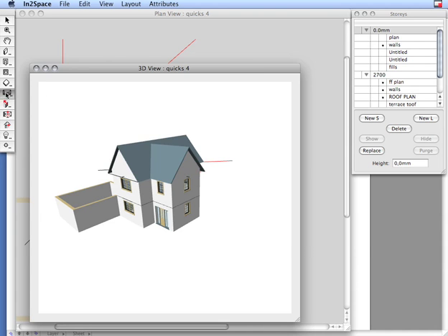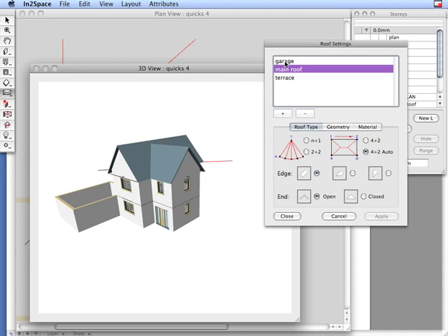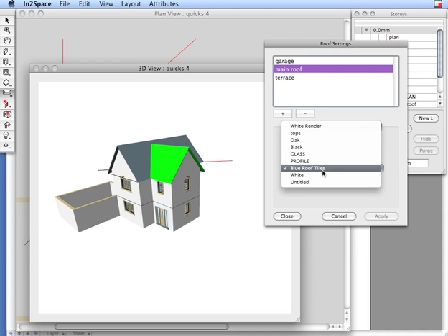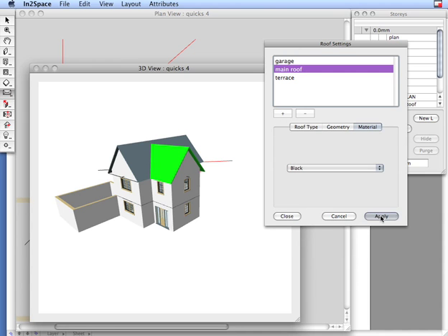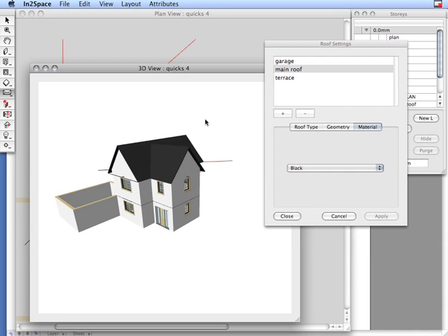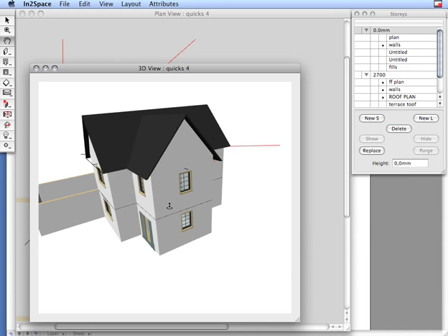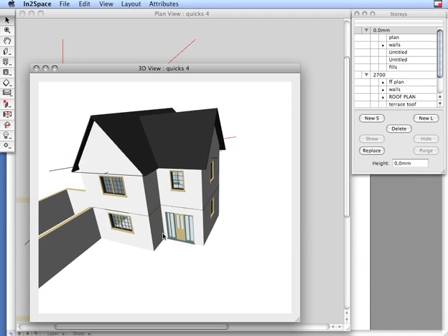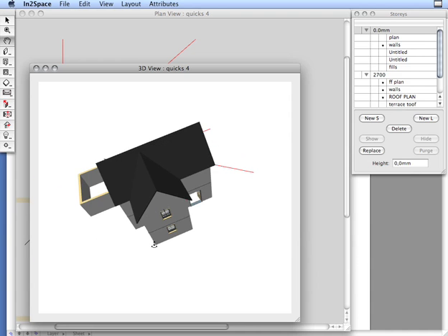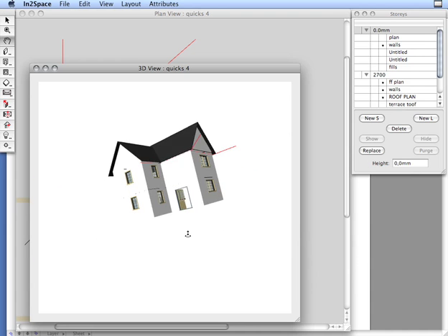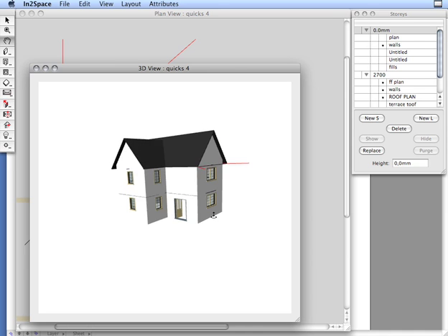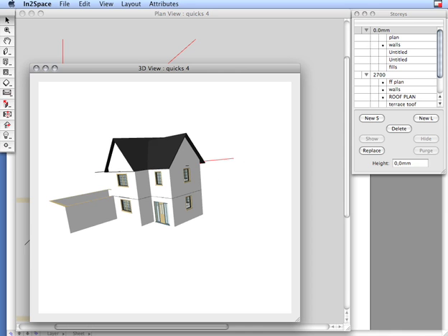We can now go in and modify. I think I've shown you before. If we click on an element, it jumps to that element within the setting. And if we wish, we can go in, change the colour of that whole thing. It's reflected through the whole drawing. And now we'll move on to drawing the smaller sort of porch roof, which is lower down on the construction.